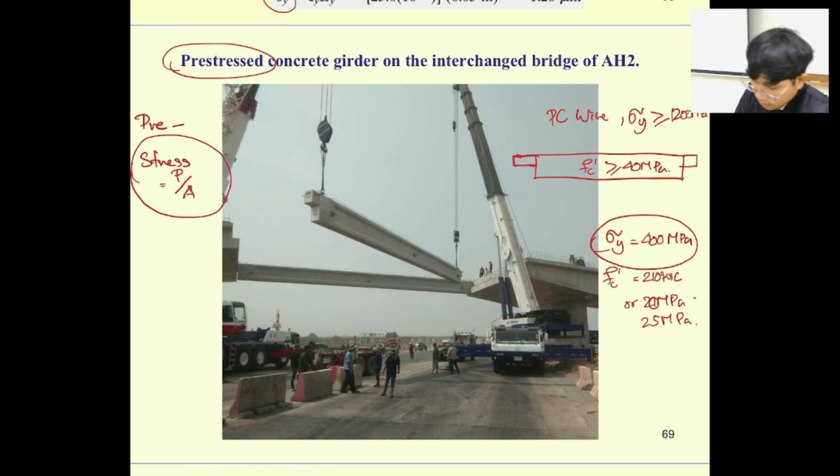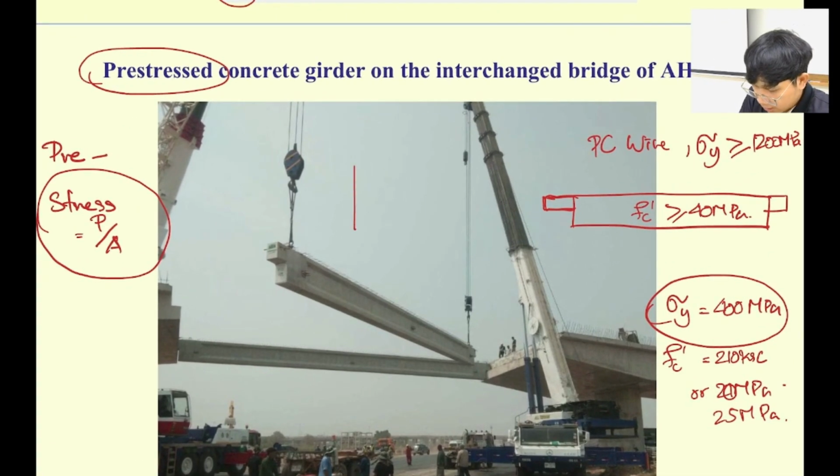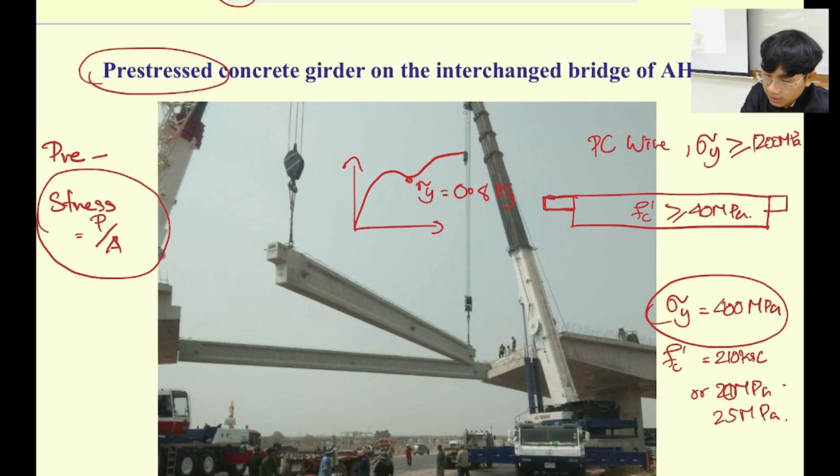Because the Hooke's law is going to be like this. And then we have, for example, sigma y is over here, we're going to use only 0.8 of the sigma y. Okay, so when we try to pull it, it's going to be somewhere between here, for example, 0.8 sigma y.